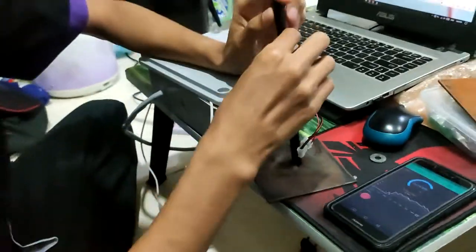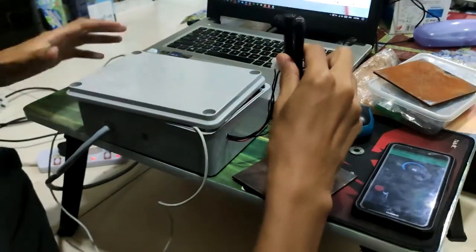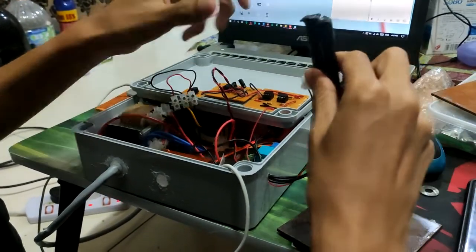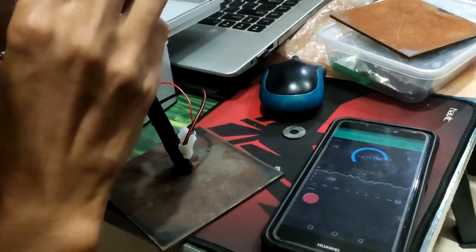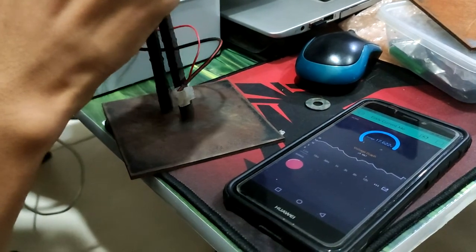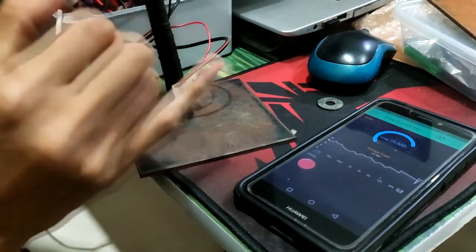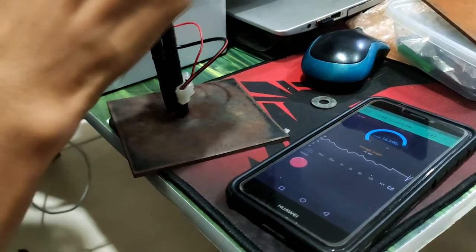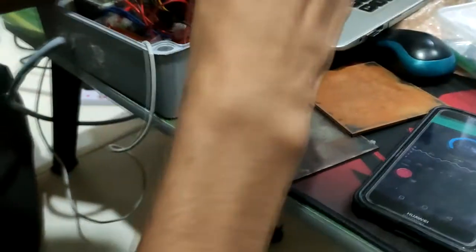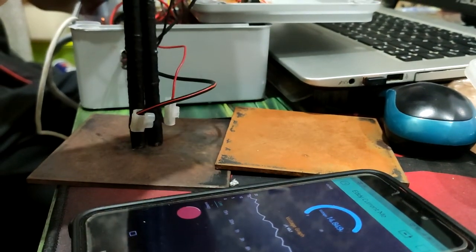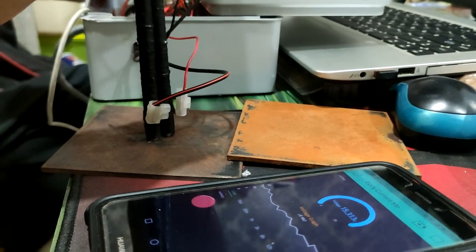But there are problems, because the amplifier has some noise or distortion, which makes the reading higher than the theory value, which must be 4.0 volts, but in the reading it shows 15 volts to 17 volts, and for the both metal should show the difference between them, but there are no difference at all, because of the amplifier problem.